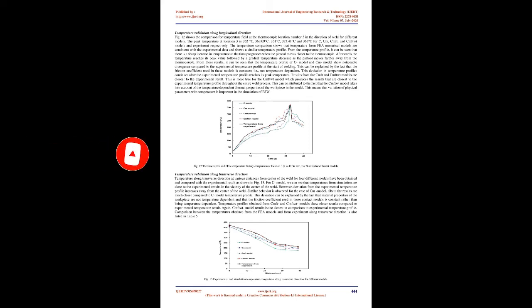In the current analysis, the distortion energy criterion gives τmax equals Y/√3, equals 0.58 Y. Y is used to identify the stick/slip criterion. Based on the modified Coulomb's model, when the equivalent shear stress is less than the maximum frictional stress, a sticking condition is modeled in the current analysis. Conversely, when the equivalent shear stress exceeds it, the contact and the target surface will slide relative to each other, i.e. a sliding condition is modeled. Contact shear stress versus contact pressure for sticking and sliding conditions are illustrated in Fig 10.